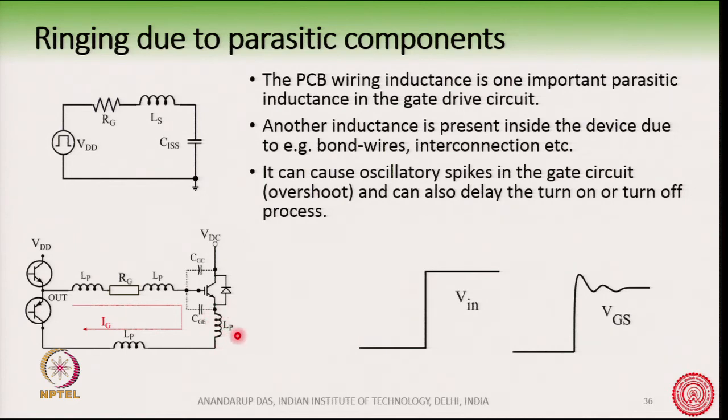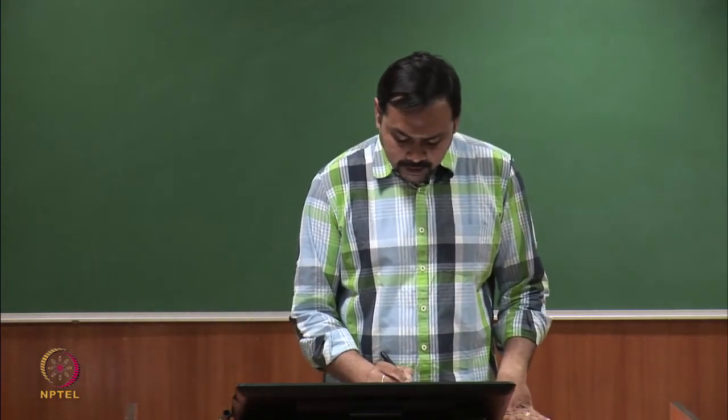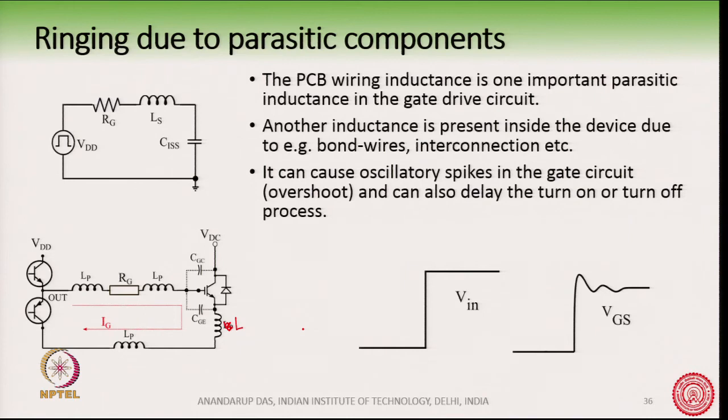Although there is a mistake here, it should not be LP, we should give it some other name, say some other L. This inductance is actually a part of the device, because inside the device there is a bond wire and there are interconnections, and so there will be an inductance inside also, and this will contribute to the total inductance in the circuit.